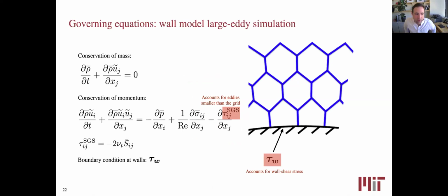This is maybe the most technical part, just the equations I'm solving. There is nothing special about this. I use conservation of mass, conservation of momentum. There is also conservation of energy, and we show that here. What is important in these equations, the U are velocity, rho are densities, and the bar. I'm using this because now this is a coarse-grained version of the system because my grid is very coarse. An example of how an actual grid will look locally close to the wall is like this. It follows a Voronoi grid.